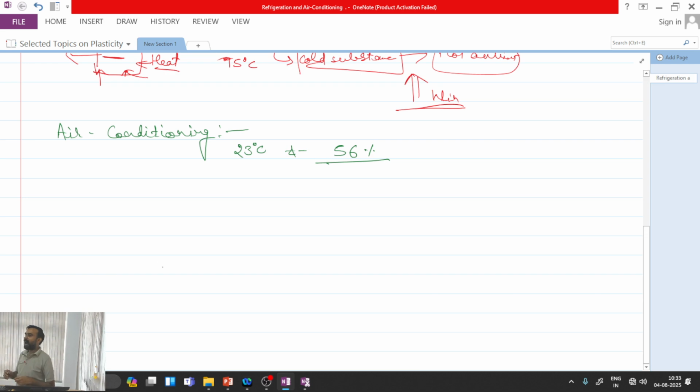But I have perfectly sealed the room so that no air from ambient can come inside the room. And I am not doing any recirculation of the air from ambient. I am just keep on cooling the room air only for a long duration of say 24 hours. Will you be finding it comfortable? Why you will not find comfortable? Yes, after some time what will be happening? It will be having more amount of carbon dioxide. So we require some optimum air quality also.